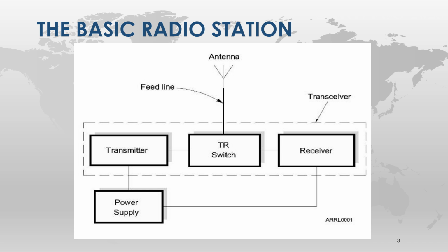So I started out with a separate receiver transmitter pair. I used a relay, so that was keyed to the microphone. And when I keyed the mic, the relay would throw, and it would go from receive to transmit. And it would block the transmit from overriding the receiver. So the receiver was already shunted to ground when the transmit came on. Otherwise you'd blow the receiver up.